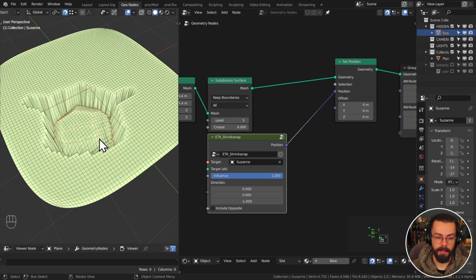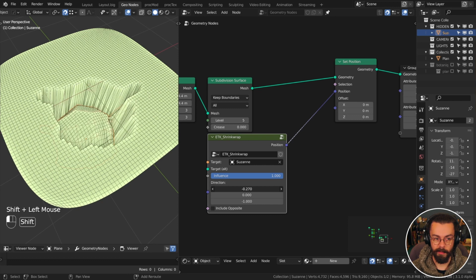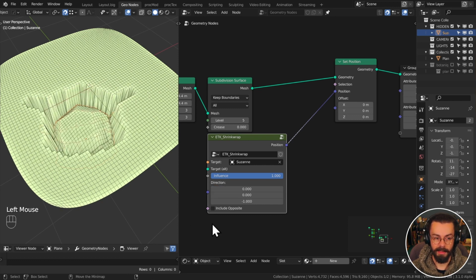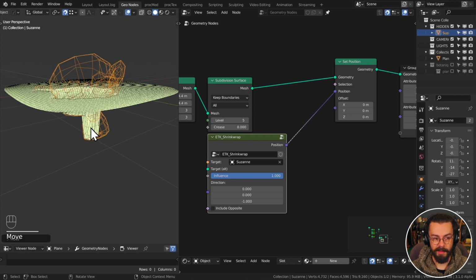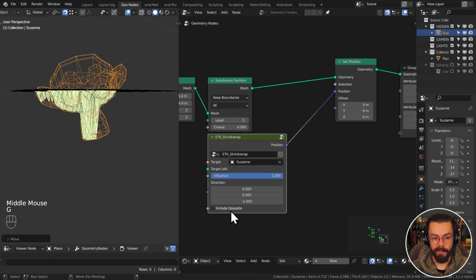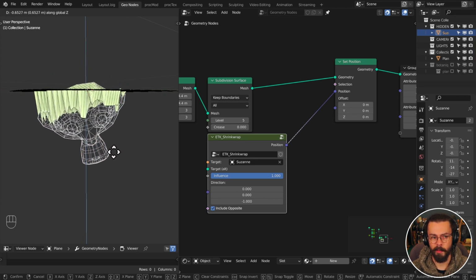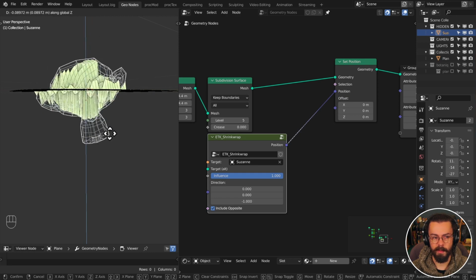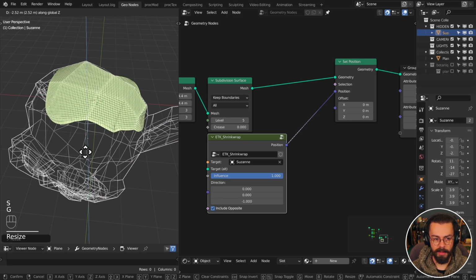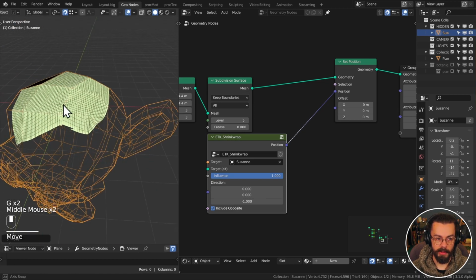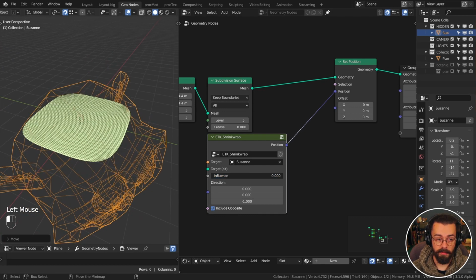Essentially, it's shrink wrapped based on the direction. We can use a different direction based on whether or not we need to shoot in a different direction. And we can use opposite. So for example, if I move this up, we can see that this is always going down, right? But if I use include opposite, it's going to use whichever one is closest, up or down. And you can see that that moves between them as we go through that. Why is this useful? Well, because if you have something like this, we can shrink wrap a surface to another mesh, which can be very useful.